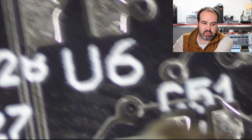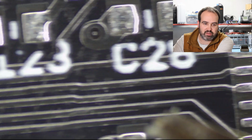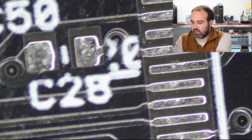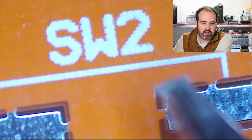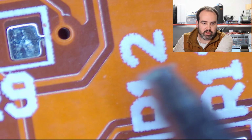Right, see this U6 is not affected, but a lot of things I just let them be as they were. But you can see the solder mask does not go over the pads. And how the solder mask is applied, by the way, can vary. You'll see different appearances. So sometimes this looks like a digital printing. You can sort of see the pixelated section here.